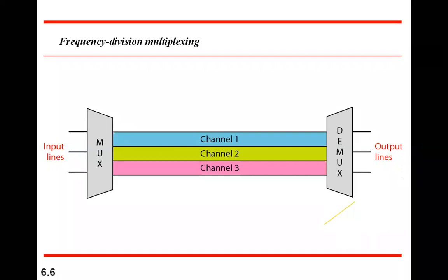So that's how there will be crosstalk. That means the neighbor's data can also get into or pass through these filters, and of course finally through the channel. That generates crosstalk. To avoid that, we always keep some guard bands between these frequencies.